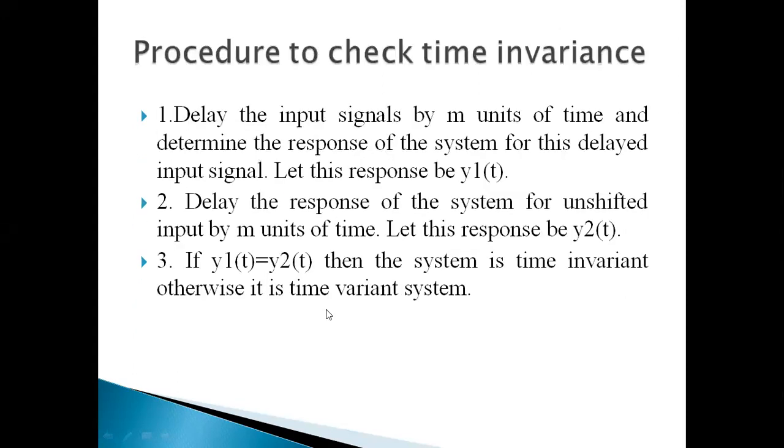Now we will see the procedure to check time invariance. So the procedure for checking time invariance of any mathematical expression is the same. So first we have to delay the input signal by m units of time and determine the response of the system for this delayed input signal. So let this response be y1t.